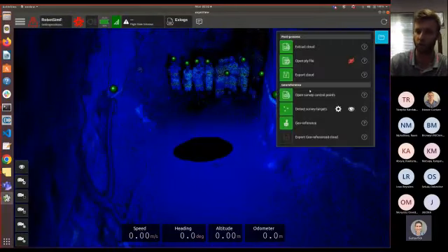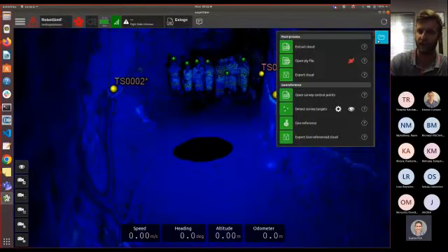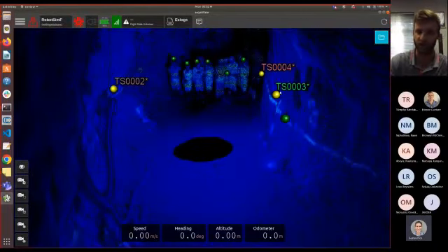Well, you don't. All you have to do is press the georeference button and let the software come up with its own calculations. And using the file you put in, it's able to come up with the triangulation and calculate which ones are the correct stations. So as you can see, I pressed the georeference. It told me it completed successfully. It's able to identify this station as being the number 2 station, 3, and 4. So we only used 3. And here, we're done georeferencing. It was a very simple, streamlined process.